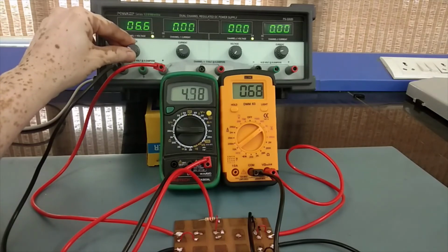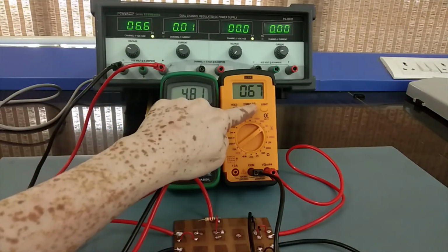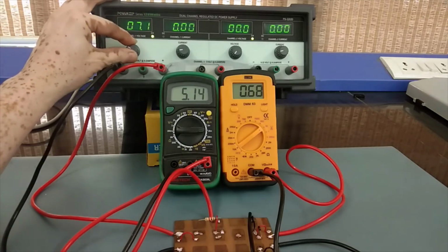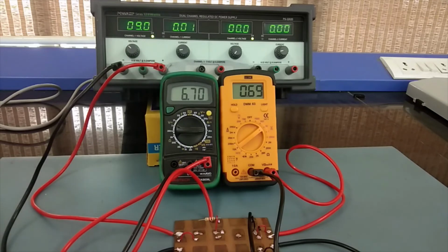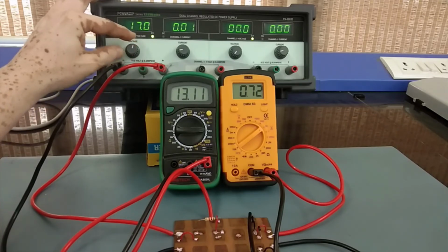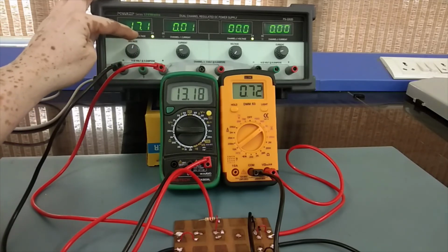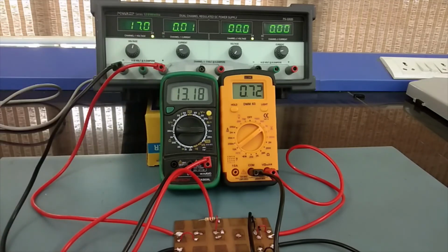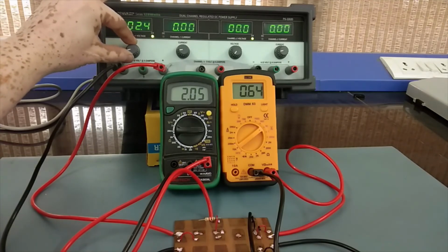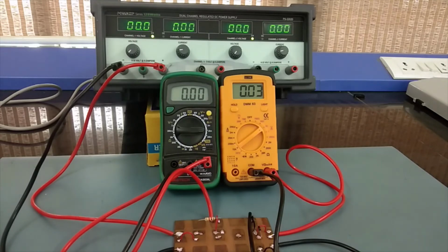As we increase the voltage, the current is increased, but voltage across the diode is increasing very slowly, or almost we can say there is no increase in voltage across the diode. So we can say that the diode has reached its conduction state. The cut-in voltage we have found, and you can see here 0.7 volt. At 0.7 volt there is almost no increase in voltage anymore. Whenever we are increasing the voltage that is being applied to the diode, the current is increasing. Okay, so the forward bias behavior of PN junction can be very easily verified in this manner.